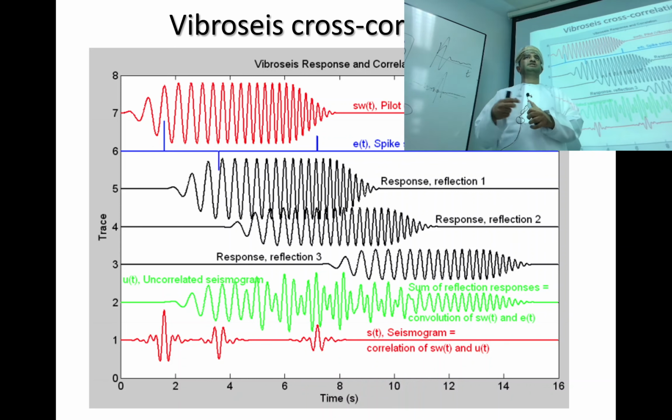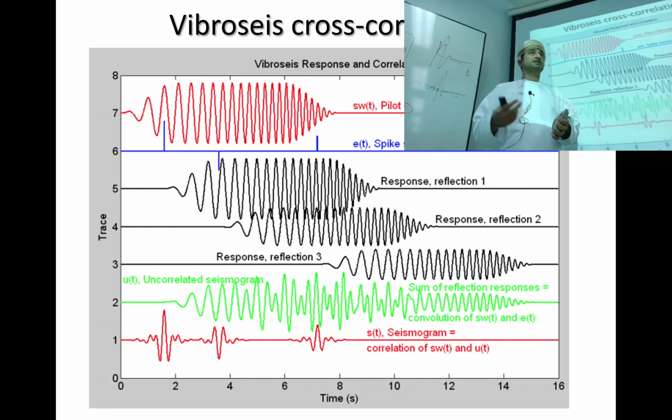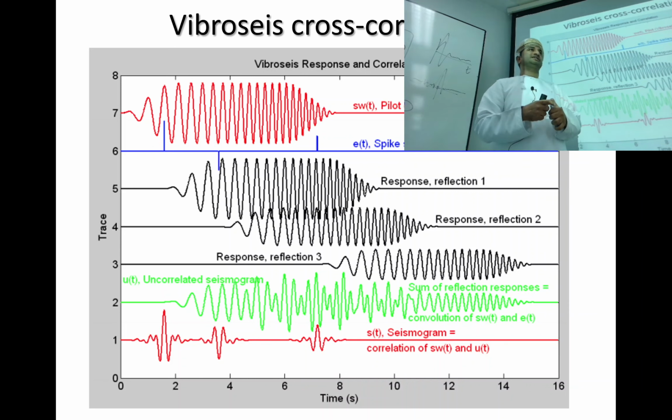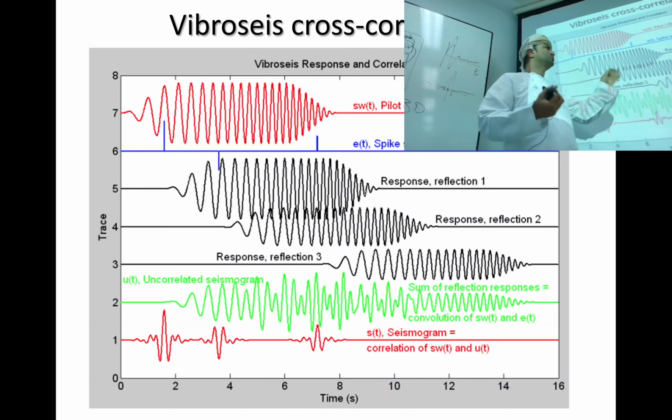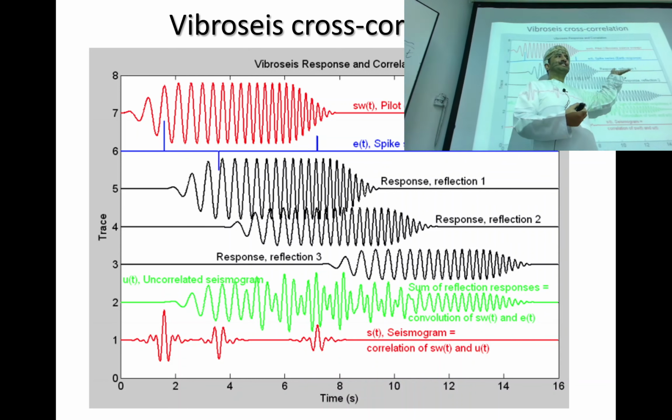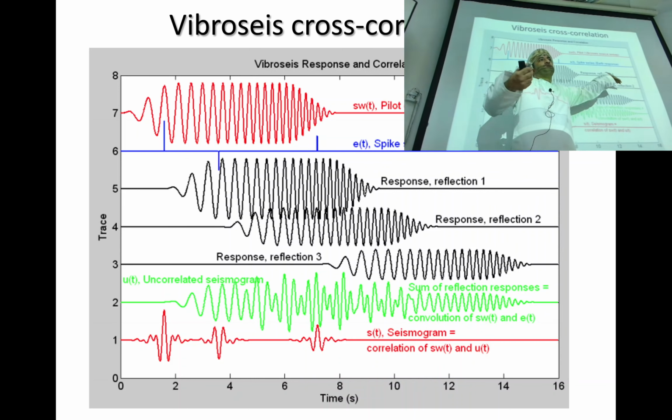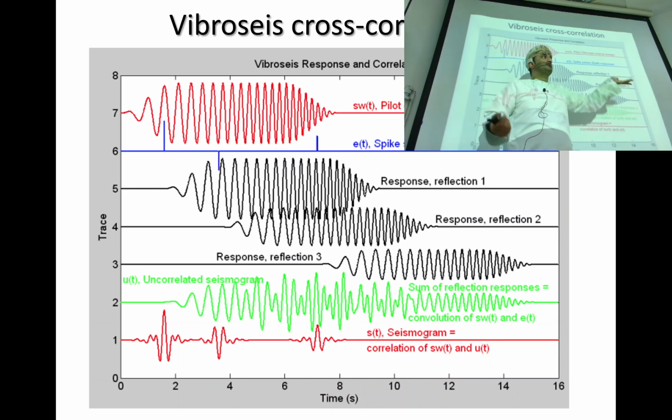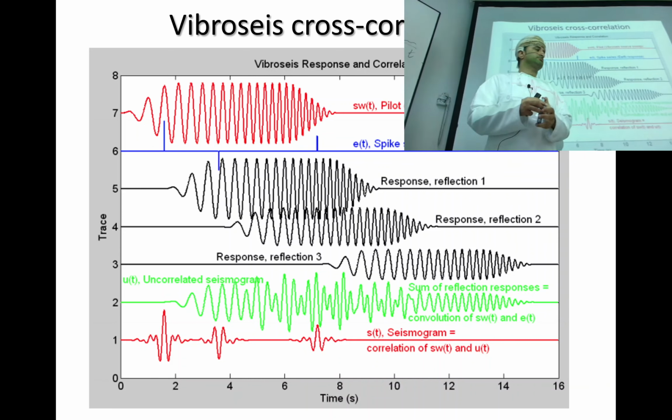Whereas if you use earthquake data, you can even image the whole earth, because earthquakes send large energy. Whereas vibroseis and hammer can only go up to 20 meters if I hit with a hammer. So I cannot go indefinitely. It's not like that.